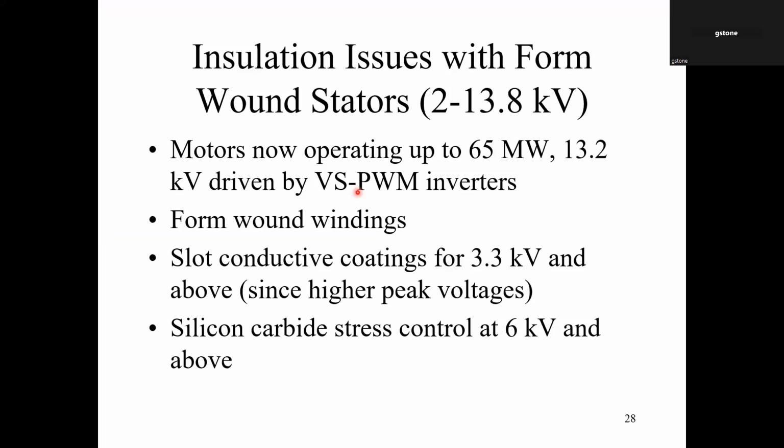Since then, there's been a tremendous amount of activity. And in fact, most manufacturers now have solved the issues with drives. There are now inverter duty motors that will make sure that they're partial discharge free at their operating voltages and with the expected surges. And we'll talk about that a little bit later. Okay, but a lot of effort happened, mainly because those motors were failing literally within months of being turned on, and certainly within the warranty period of the motors. So the OEMs were highly motivated to try and fix that problem. And I think they largely have by better impregnation methods.